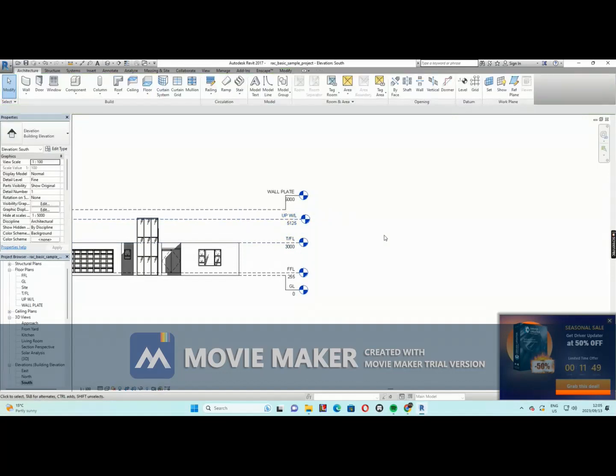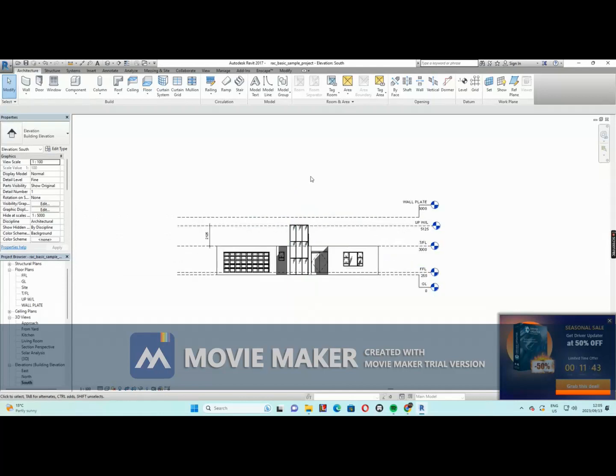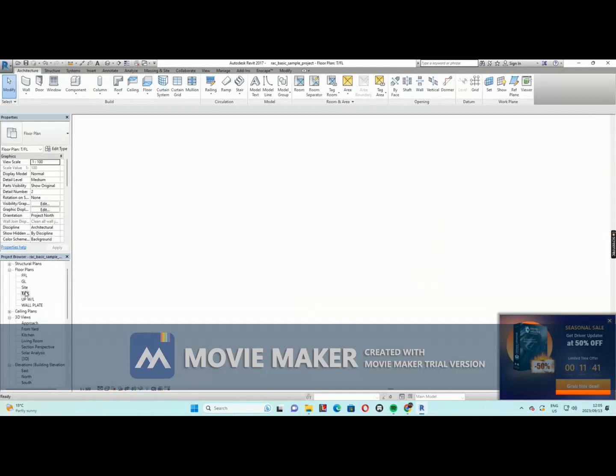Now, we want to extend these walls to go to top. You can go to top now. You see nothing. Here, you just see stairs because our walls are ending on the first floor. So what you have to do now is go to your view range.